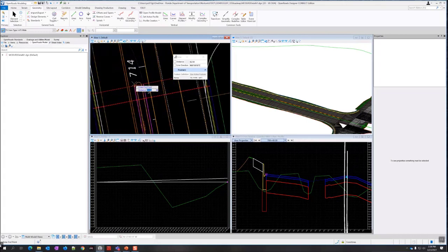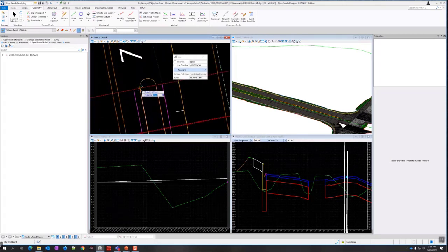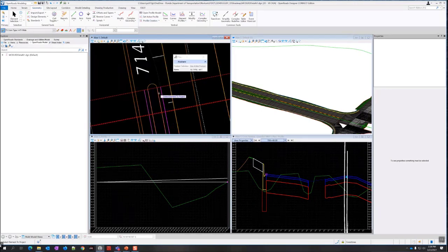Snap that line and snap that end of it. Okay, so my lines are in there. They don't have any profiles right now. So I need profiles on all of these. So if I go to profile creation, I should be able to just do project profile to element. Range would probably be cleaner, but I'm going to just try this since it's quicker.